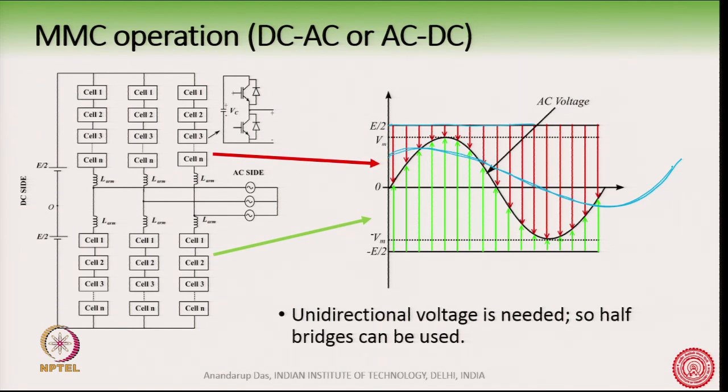First thing, it will be possible to operate the converter, because now if the line is something like this, then the arrows can produce this blue line. Arrows are nothing but controllable voltage sources. So, the arrows will now be changing like this, and they can produce this voltage. The arrows must be bidirectional in nature, because sometimes the arrows will be positive and sometimes negative.